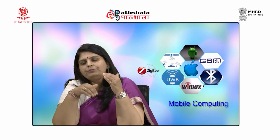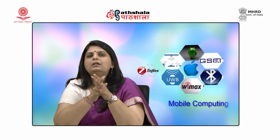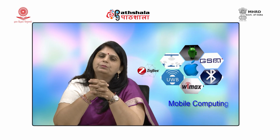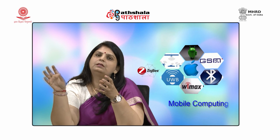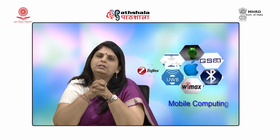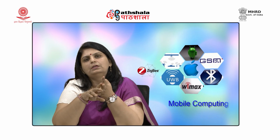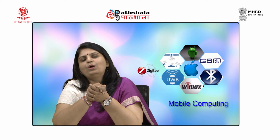Now, when the signal, after undergoing these phenomena, reaches the receiver, instead of following the direct line of sight, they take different paths, they get attenuated, and these paths are known as multipath components. Each component arrives with different amplitude, with different phase at different times, due to which the phenomena delay spread and intersymbol interference occur. To minimize the effect of multipath propagation, MIMO, that is multiple input multiple output, OFDM and rake receiver are being used. So, this is all for today's module.